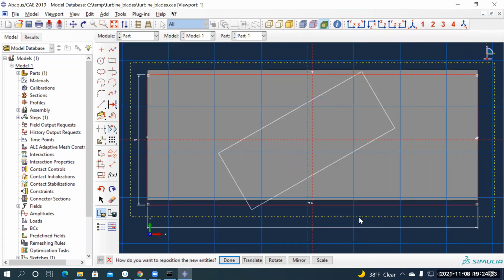And it is of the previous, so let's scale it, scale about origin 0, 0. Let's scale it to 25%, 0.25. Okay, you want me to repeat it? So when you add in the sketch, it asks you to scale. So choose the scale option, enter origin 0, 0, then scale factor of 25%, which is 0.25, enter.